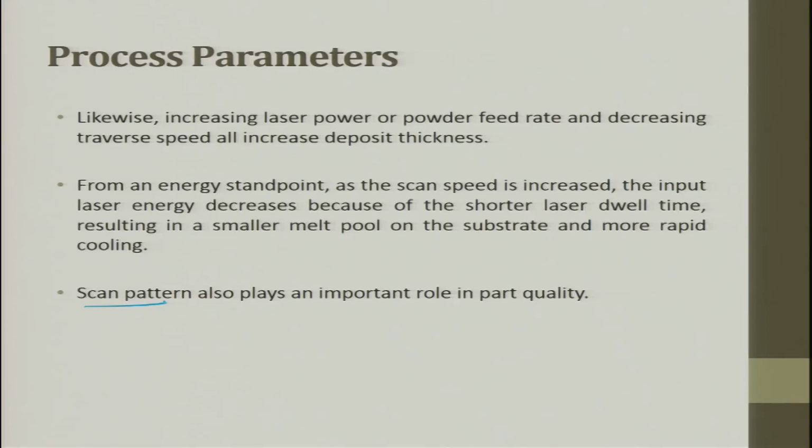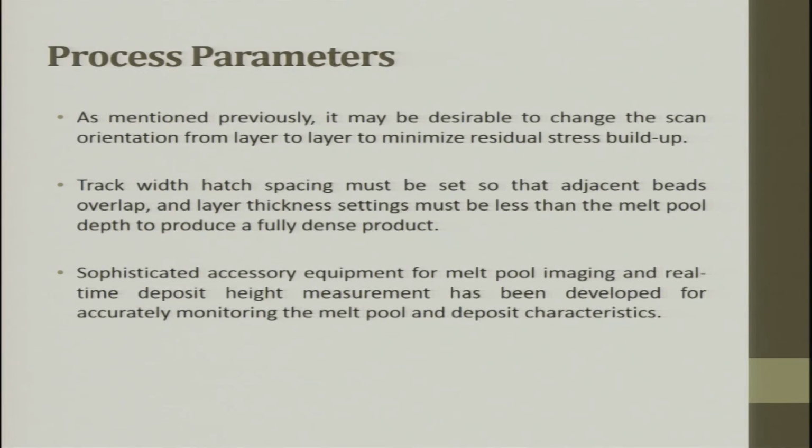The scanning pattern also plays a very important role in the quality of the product. It may be desirable to change the scanning orientation from layer to layer to minimize the residual stress build-up. That is why we saw earlier the 0 degree, 90 degree and 45 degree orientations. The track width and hatch spacing must be set so that the adjacent beads overlap, and the layer thickness setting must be less than the melt pool depth to produce fully dense products.